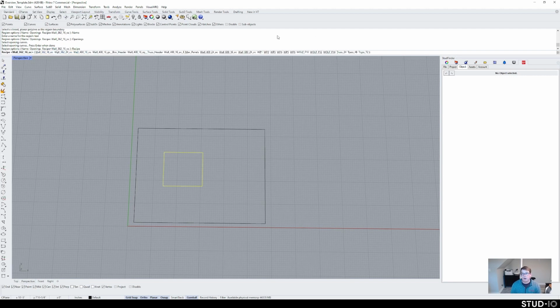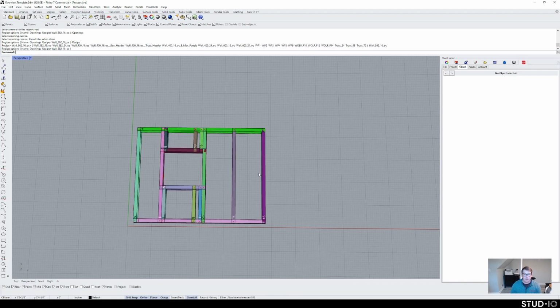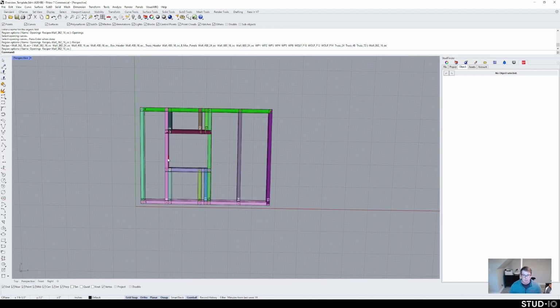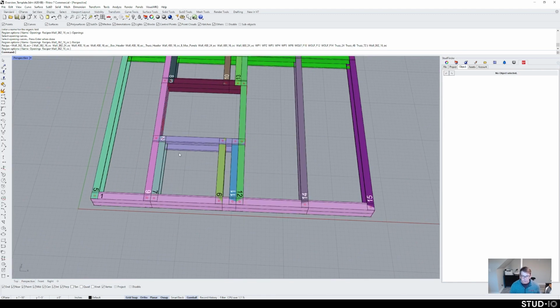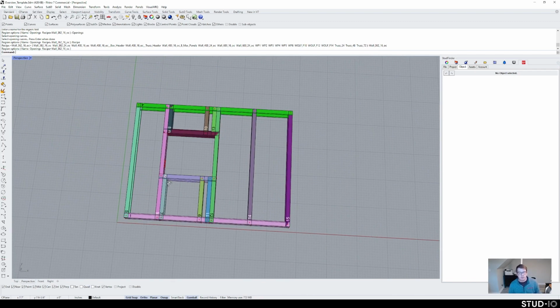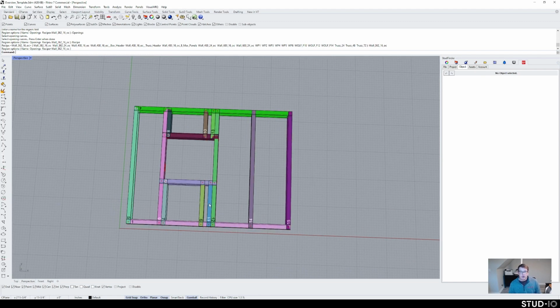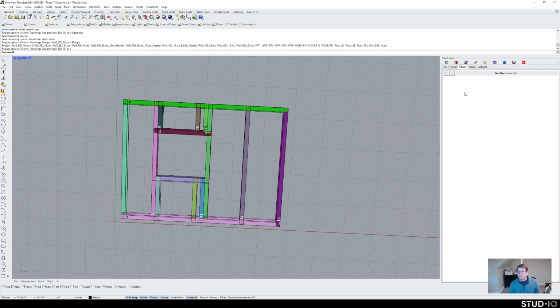So we ship a number of recipes out of the box. So this wall 3 5/8, 16 inches on center is good for now. If we hit enter on that, you can see that this built us a little mini panel that is 3 5/8 inch stud, so stud and track. In this, the top and bottom of the panel became track. All the vertical studs became studs, of course, so C-shaped studs. And that quickly generated our stud layout for us.